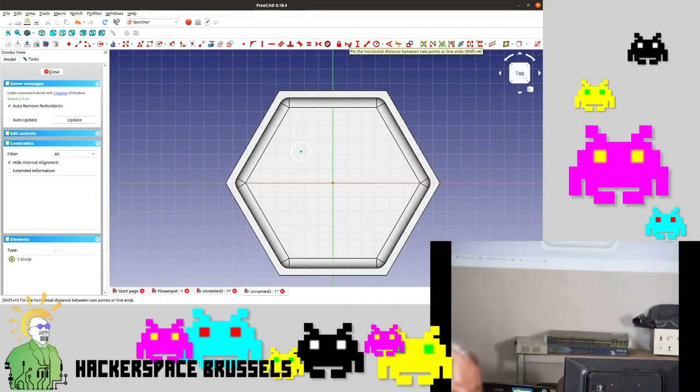The only thing is, if you're looking from the bottom, your plane may be on the other side, and sometimes you don't see the stuff. So for conformity, I would advise to go the other way around. Select the bottom, and then click on new sketch.